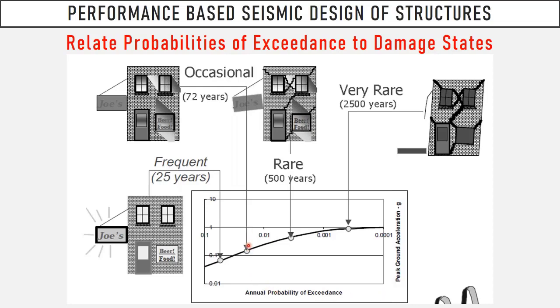And what's your expectation, or what's your criteria in terms of probability and the damage state? And of course, you need to define it with a so-called annual probability of exceedance. It's not just saying that with rare events you will have full operations, or in design-based earthquake you have life safety. What is your definition, and what is its probability?